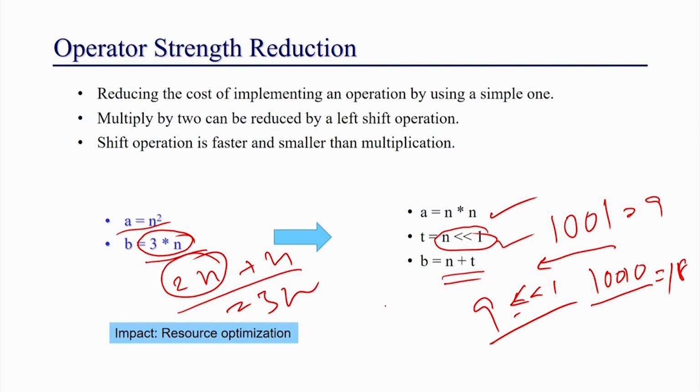So, instead of using a multiplier, I am using a less costly operation, shift. For a shift you do not need basically any operator. You have to just do the bit manipulation, shifting the whole thing by 1 bit. You do not need any adder, multiplier or any kind of resource to do this. You just shift and reassign the values to these bits. You have to just do A1 equal to A0, A2 equal to A1, A3 equal to A2 and so on, and it will automatically do the shifting.